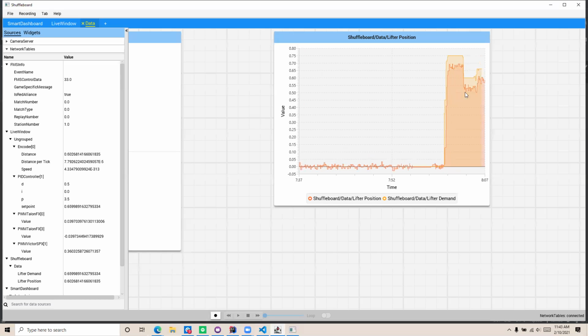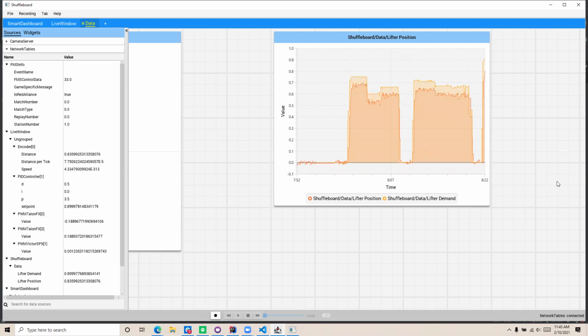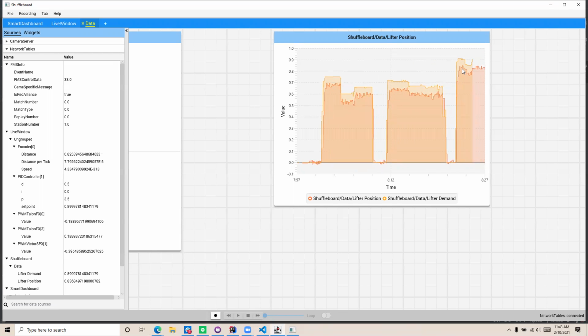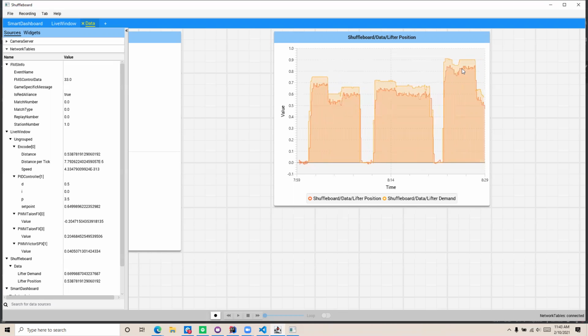You can see here that it doesn't really oscillate that much anymore. You can see that it slows down a bit, but otherwise it doesn't overshoot or undershoot at all. So it looks like, you know what? This is a good number. If you're lucky and you get it right on the first try, there's no need to change it, right? Okay, but as you can see here, you might have noticed that we're ever so slightly off the target, right? We're always underneath that joystick curve, right?